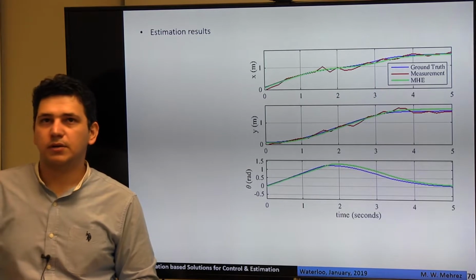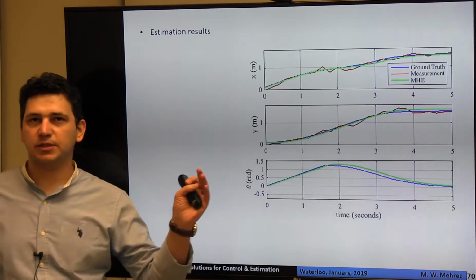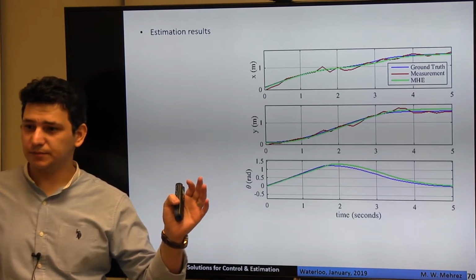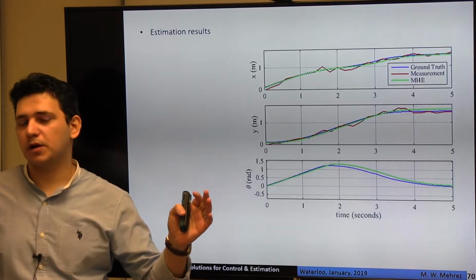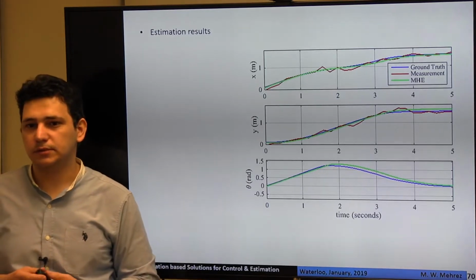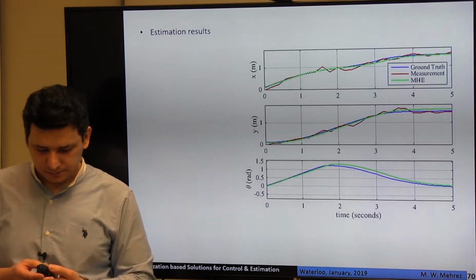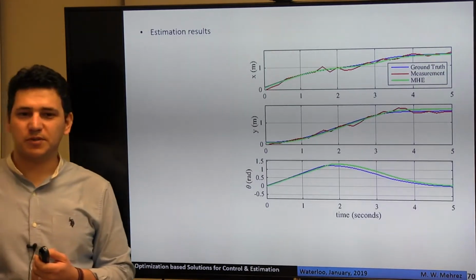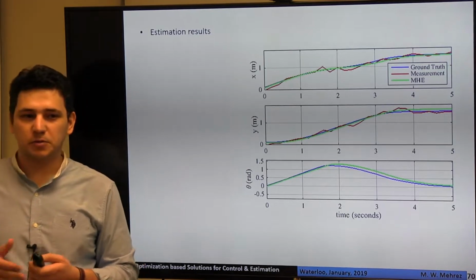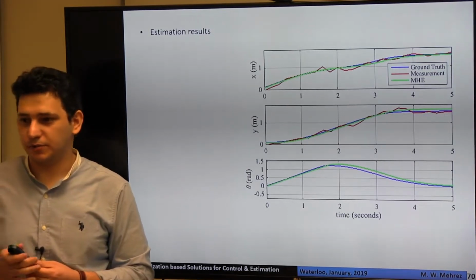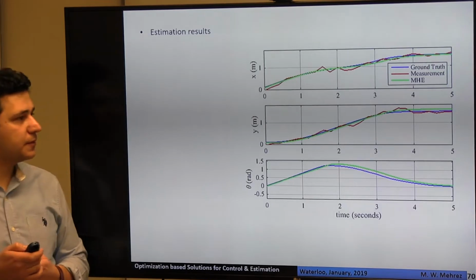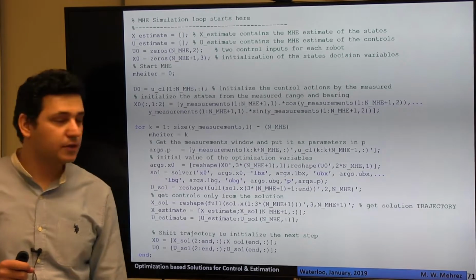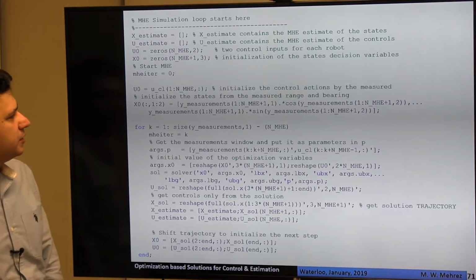Here I remember that for the whole simulation time we have NMHE equal to roughly 26 or 27. So compare this to a prediction horizon of 27 or 26. And if you remember yesterday, when the prediction horizon was already 100, multiple shooting worked pretty well for this problem, right? Okay. So now let's do the same thing, but in a receding horizon fashion. All right?